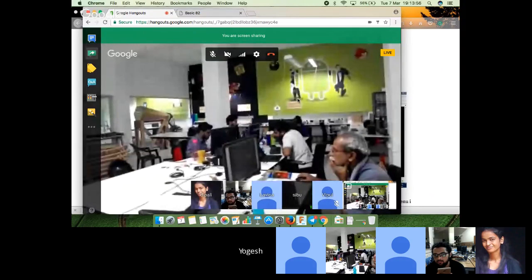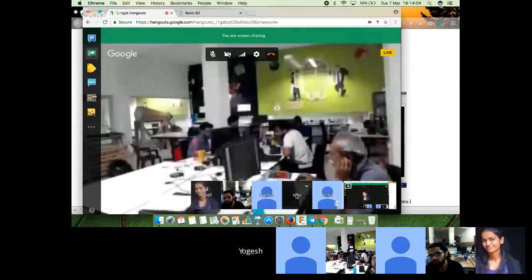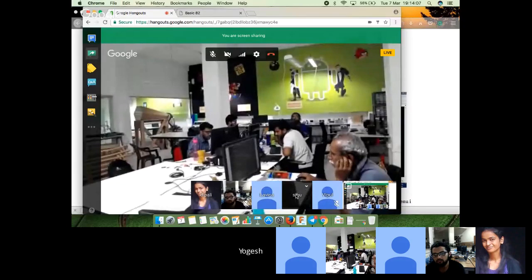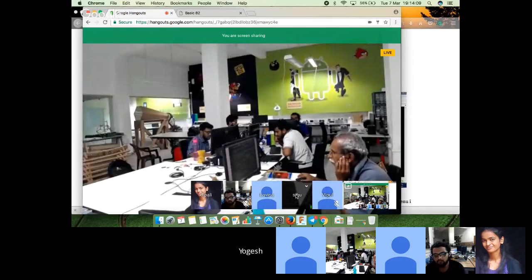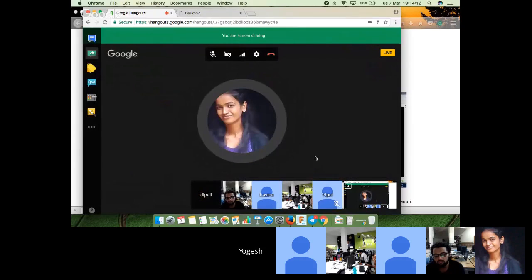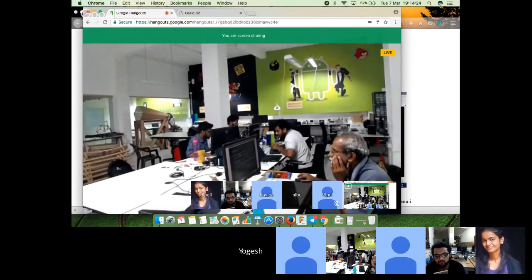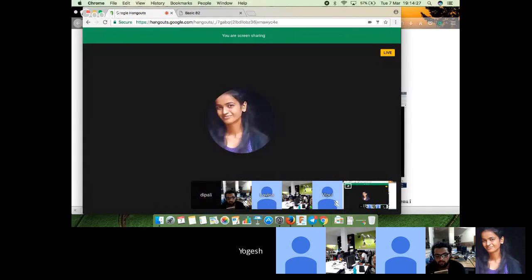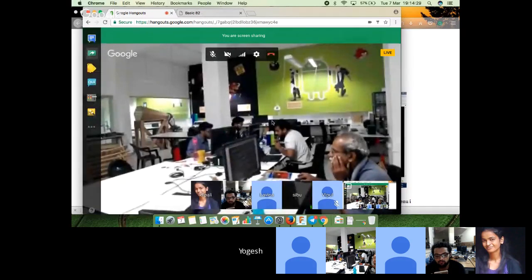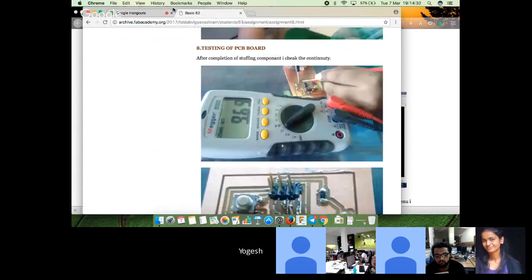Yogi, just a minute. I think she's trying to use Arduino to program the board, right? Yes. But why are you using Proteus in between? She was trying to simulate, I think. Yes, I want to simulate. Okay, so let's get things clear. There is a simulation part, leave that for now. Now for the programming part, you made the program in the Arduino software and are using it to upload, and you are not able to find ATtiny44 in the list, right? Yes.